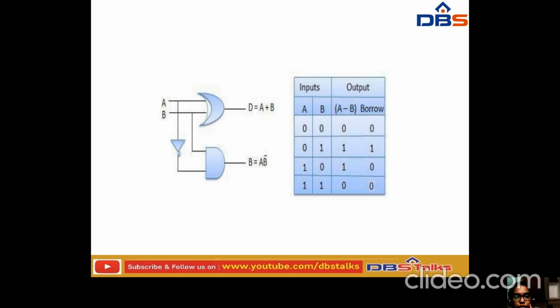We can easily use this type of circuit. See, here we have performed the AND operation, that is a plus b, and from this input we have applied the NOT gate here. So the second input is b bar. Okay, why? Because we have applied the NOT gate here, and the next one is a. So for this the output is a b bar.